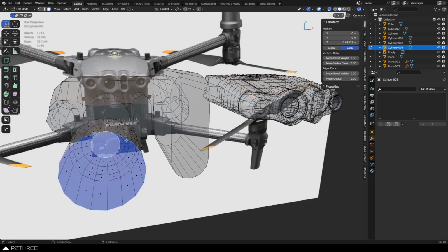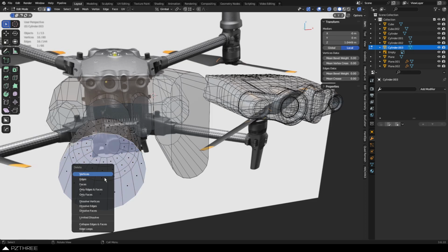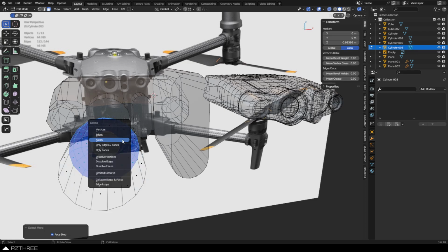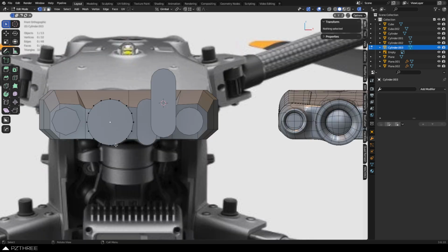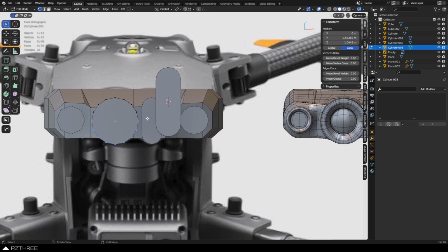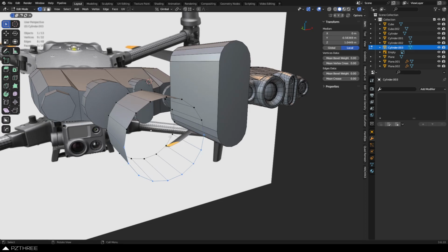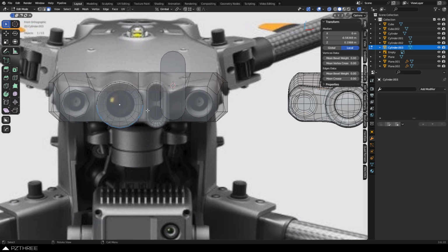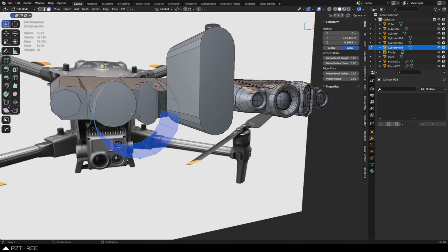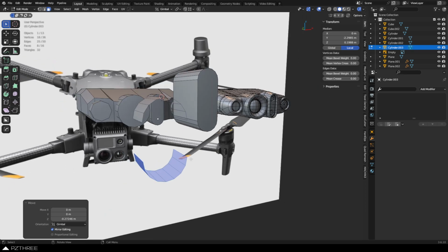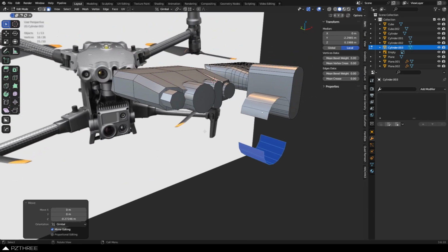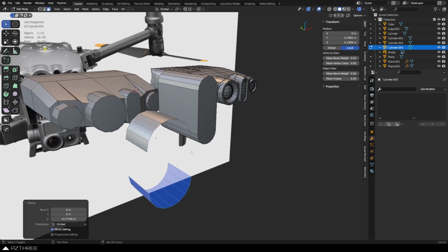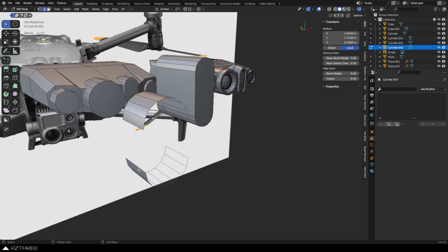So if I was to take all this here and delete it real quick, let's delete the front side first. And we get rid of the back for just a second. If you take these vertices here, or these faces, should I say, probably better to do it with the faces here. We press Y to rip it. We can hit G and Z, we can move it down. This is virtually the same idea as creating that pill shape there. So you can see later on, you can actually take something like this and attach it back together.